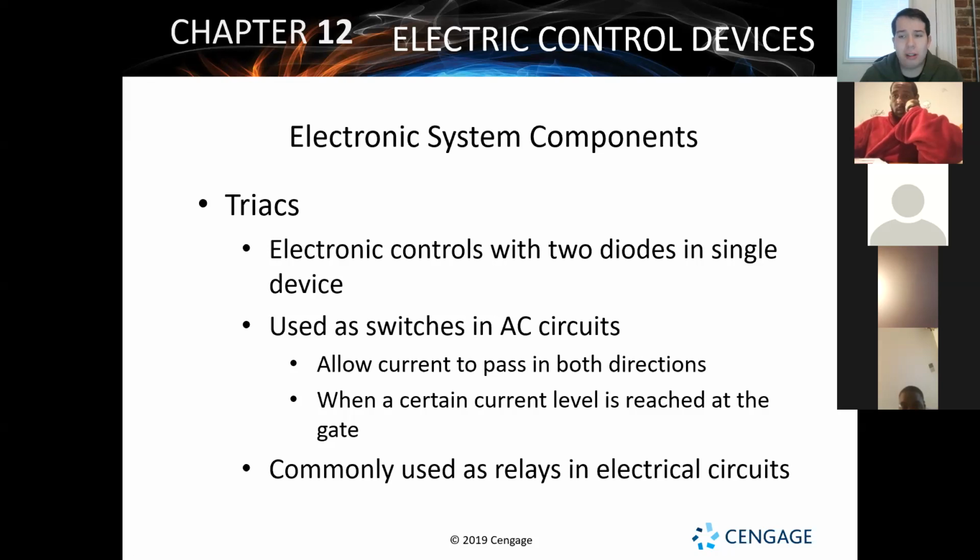They might have a multi-purpose or universal control board on their truck that they can keep using again and again, or for a couple of different units. But typically, it's just best to understand what that control board's doing and how to troubleshoot it. Towards the end of this slideshow we'll talk about what we call the black box method. That's basically just checking voltage in, voltage out. But we'll talk about that more as we keep going through.